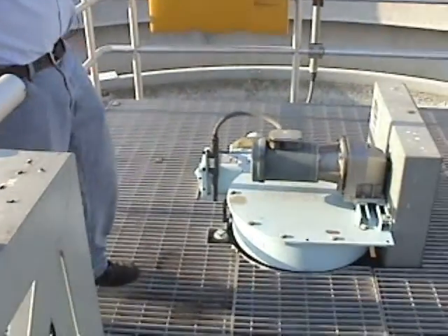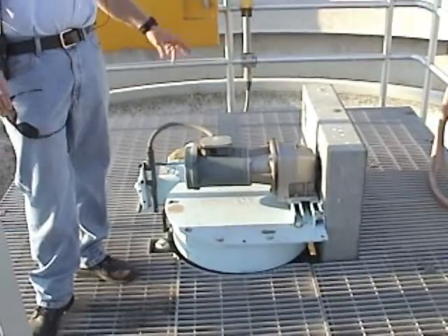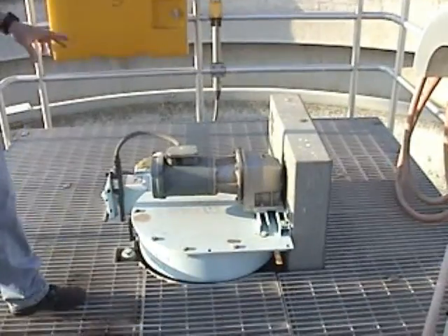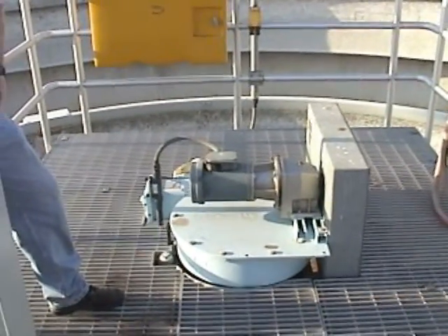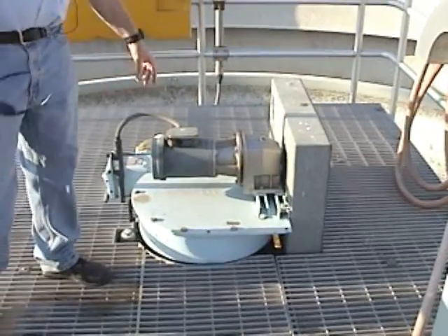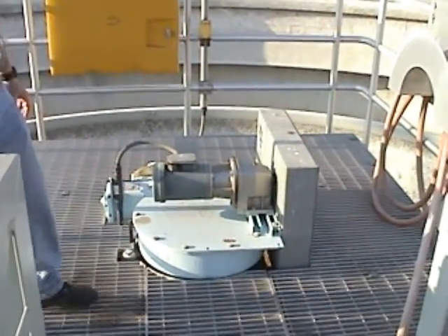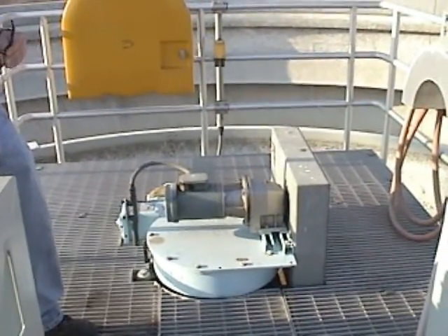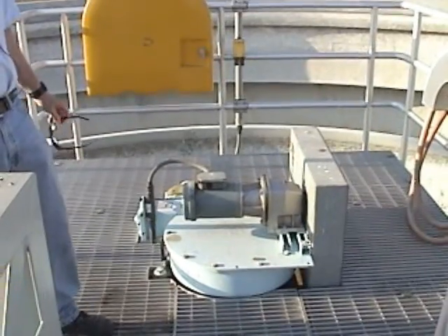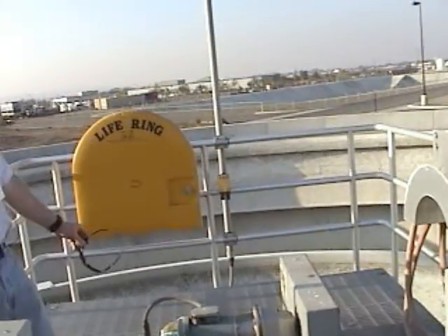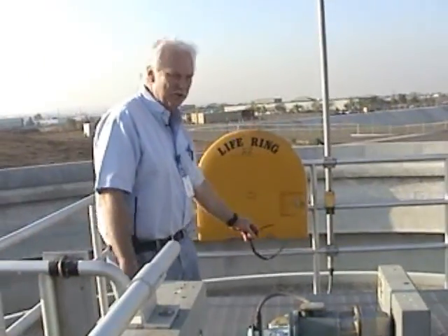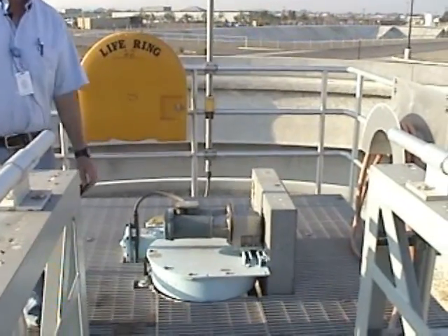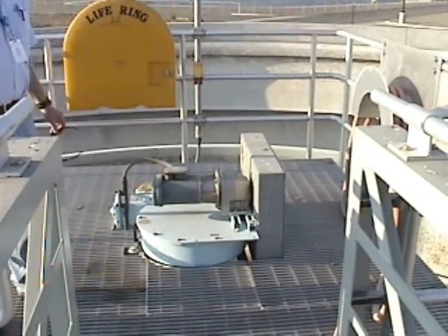And let's see, on the Foxboro system, when this is on, you'll see it. You can't turn this off or on remotely, but it will give you a run indication. When you bring up the secondary clarifier details on the Foxboro system, if this is running, it's going to be red. If it's down, it'll be green. So that's really handy when you're starting up the plant, particularly after a power failure, which is probably the biggest thing that happens here. The most difficult thing to handle is a power failure. You can go through your SCADA screens and see what's running or not. So you should see 2 of these red, which would be clarifier 3B and 4B.